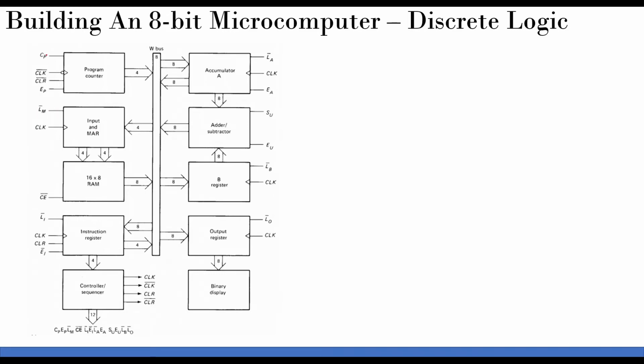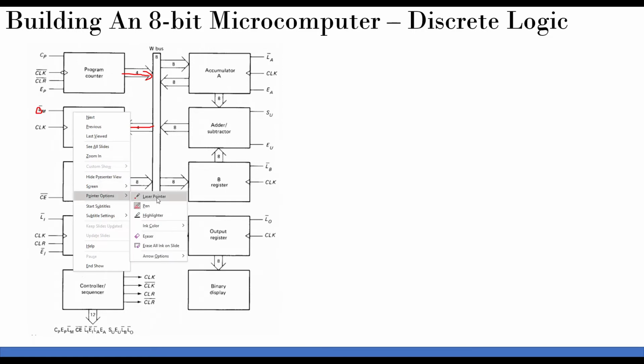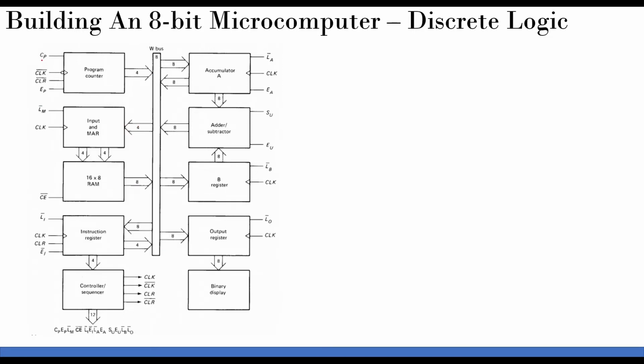Okay, and then all these control signals are either to connect the component to the bus or the reverse direction. You can see the direction of flow is from here to here in this case, but here to here in this case. Whenever we are getting the data from the bus to the particular component, we typically use the suffix L. I will reiterate it later when we explain the circuitry, but I thought I'd explain the reasoning of these names.